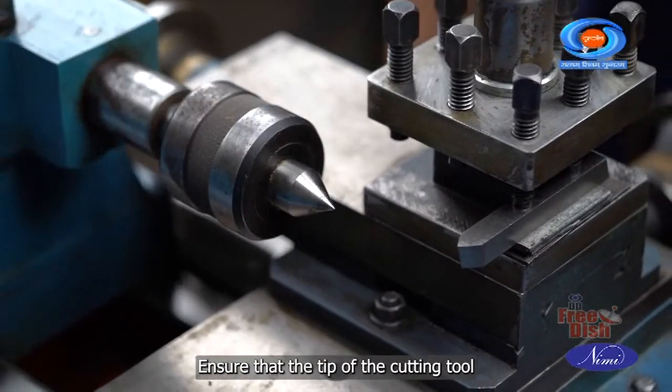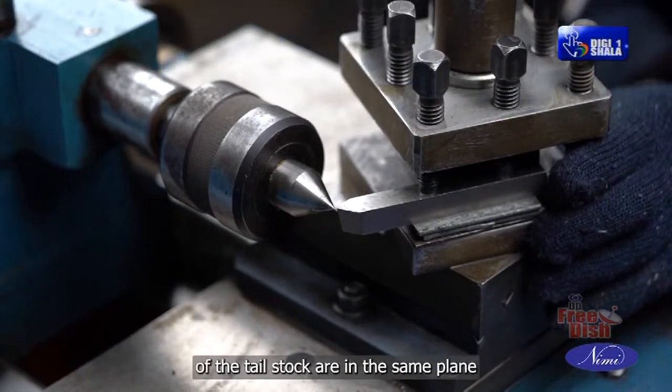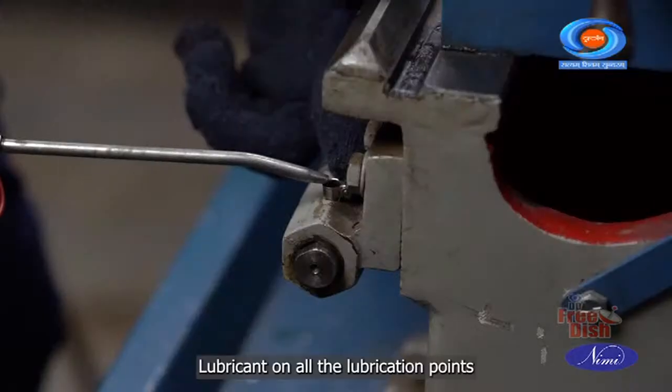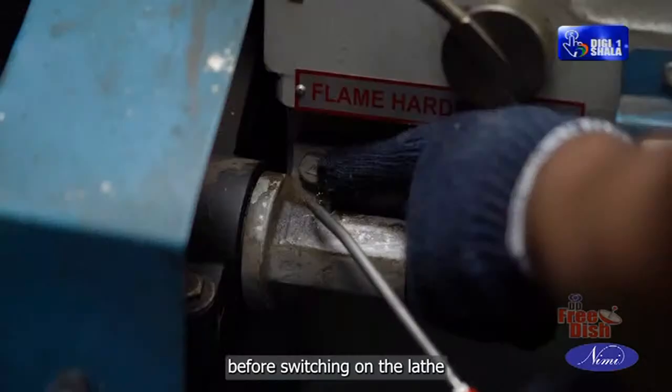Ensure that the tip of the cutting tool and the tip of the center of the tailstock are in the same plane. Lubricate on all the lubrication points before switching on the lathe.